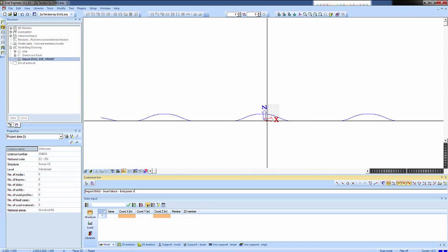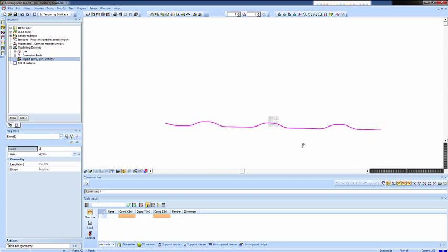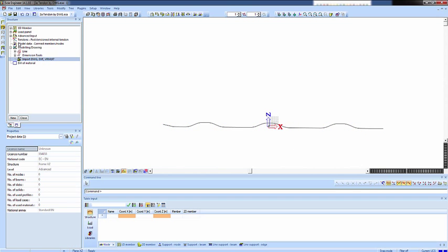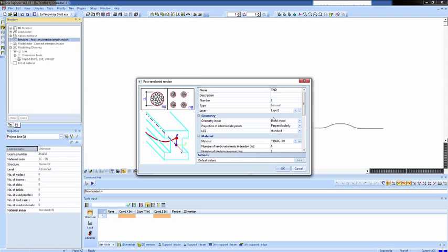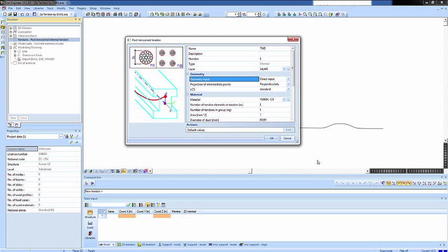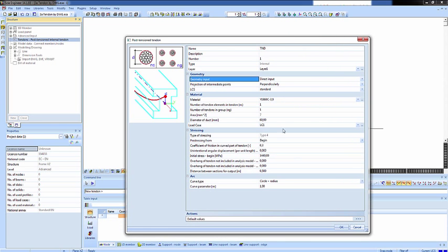Now, of course, this is a very long tendon. This is no more than a line. Now, to input my post-tensioning, you can see here I have tendons, post-tensioned internal tendon. I'm just going to pick direct input. Now, in the properties, I will show you this window. In these properties, I can give extra properties, for example the material which I'll use, the number of tendons I will combine, and how many groups I will combine. Also which load case I will input it in, and how the stressing is performed. Now, for my material, you will see here I have this C, that means a cable.